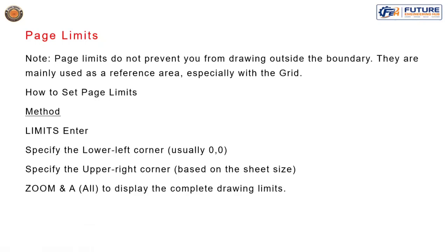Specify lower left corner, usually 0,0. Next step, specify upper right corner based on the drawing sheet size.